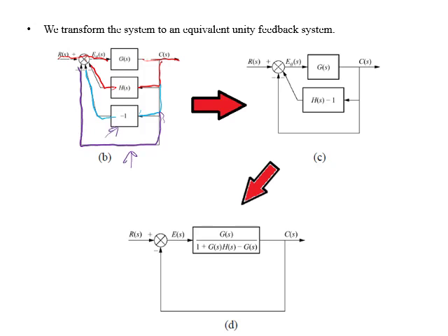Okay, after that, we find that we can use block diagram reduction here to simplify or rearrange the blocks. See, these two are parallel, so we can join them together. So they are going to look like here, H(s) - 1. And the unity feedback, we will keep it. We will not touch it. So the system will appear like this. This is the feed forward, and this is the feedback.